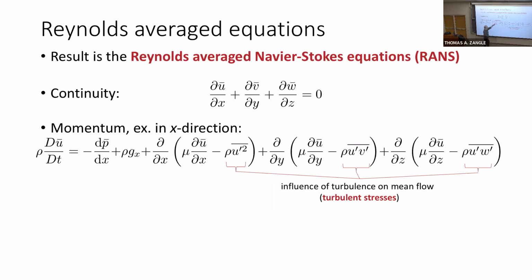What we care about is u bar, and these terms tell us how the turbulent velocity fluctuations, all the fluctuating components of x, y and z velocity, feed back and affect the mean flow. This is why the velocity profile for turbulent flow in a pipe, which we just saw in the video, is different from the velocity profile for laminar flow.